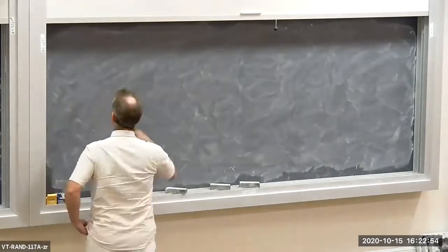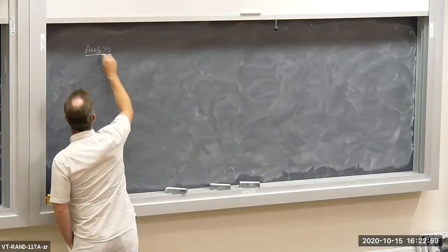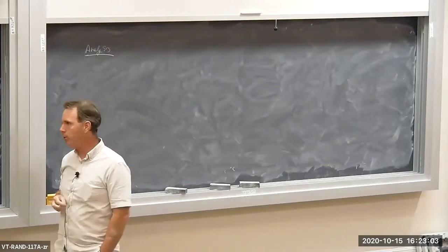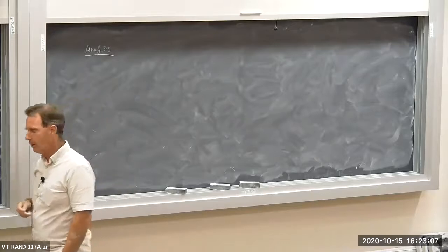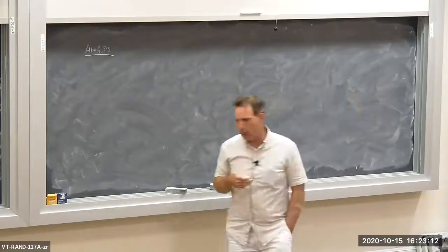So, analysis. I don't know anything about state 2 except pressure. I do know at state 2 what the pressure is, but I don't know what the enthalpy is at state 2, which is the pump outlet state.